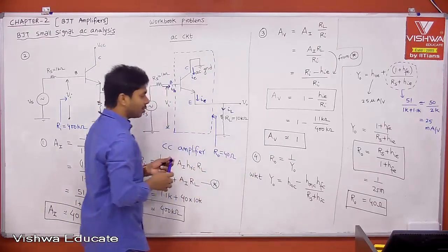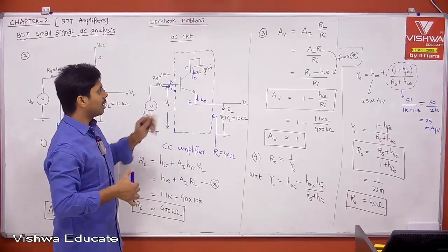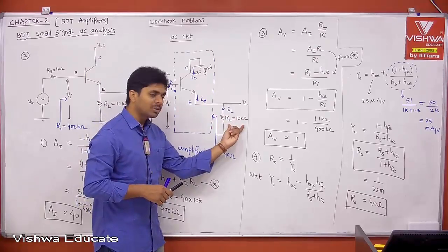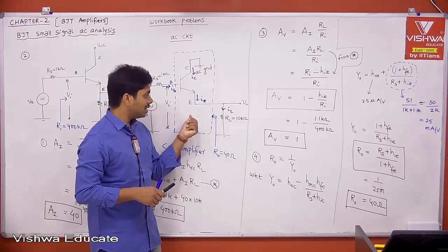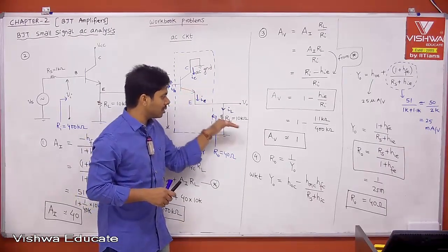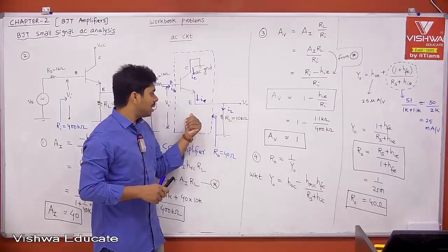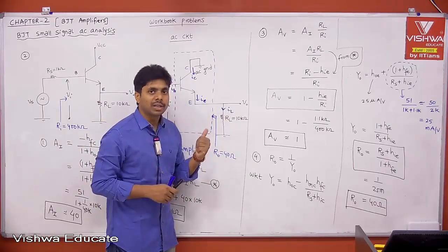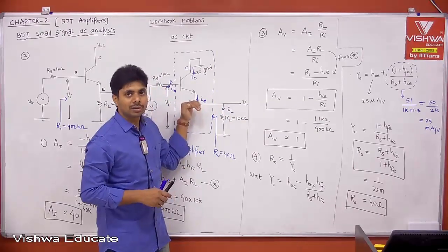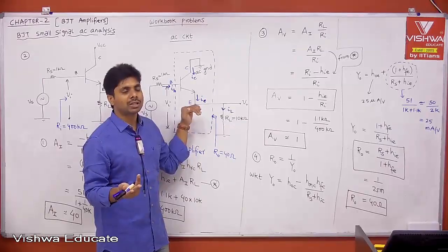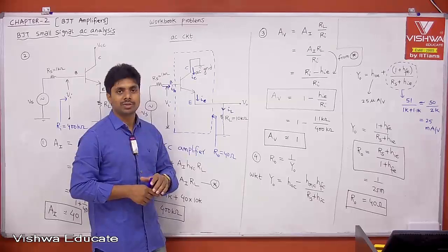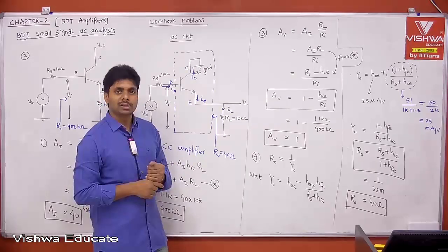What does it mean? I told you, think of a loudspeaker and an audio amplifier. Your amplifier is the source for your loudspeaker. Can I say it that way? If I speak about voltage signals, then that amplifier is giving voltage to your loudspeaker, so your amplifier is a voltage source. But whether it is an ideal or a practical voltage source is defined by your R0, where R0 is nothing but the internal resistance of the voltage source. You can treat it that way, right, for voltage signals.